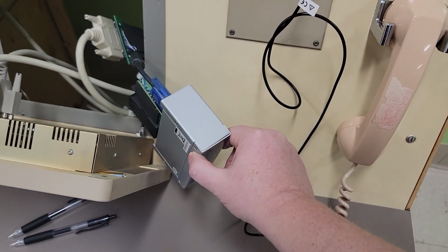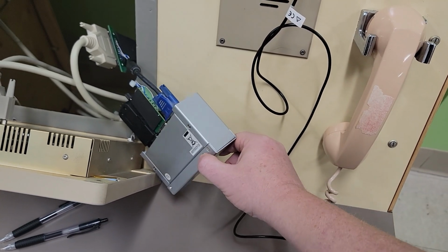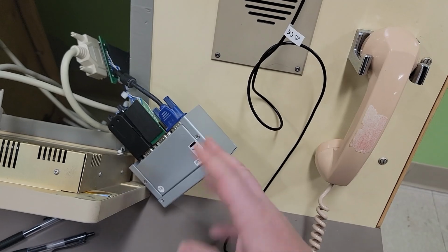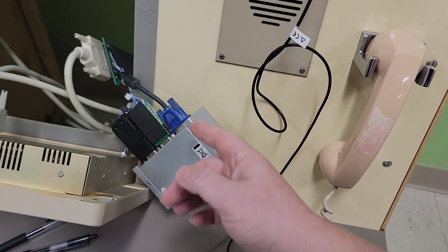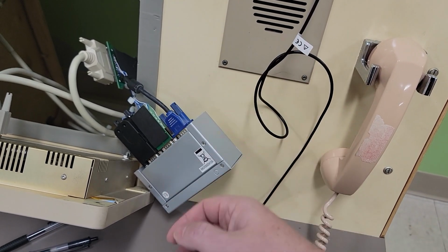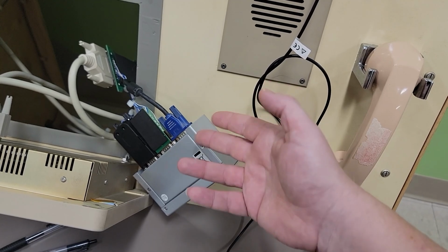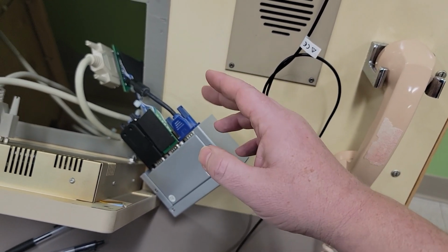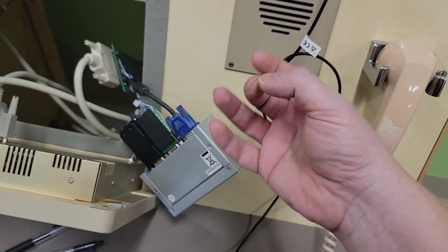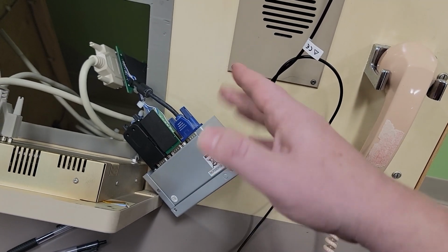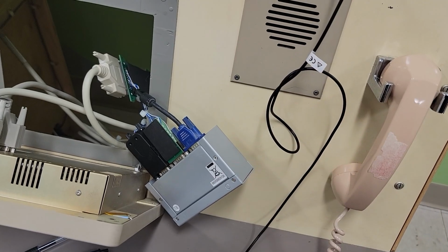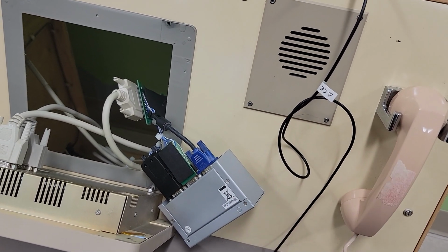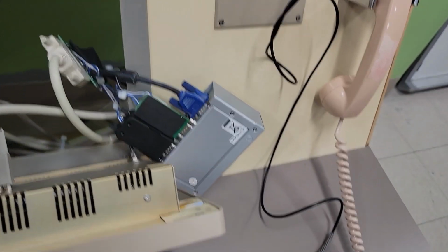a video splitter. Those of you who are old enough, y'all remember these devices. VGA usually had like 2 or 3 different formats. It had RGBHV, which is what we're using here: red, green, blue, horizontal, vertical sync. Or it had RGBS, which was combining your horizontal and vertical sync together into one sync signal. And then there was a third option. I can't really remember what it is off the top of my head. Those of you who can, at least a third option, you can scour the internet and look for it for yourself.